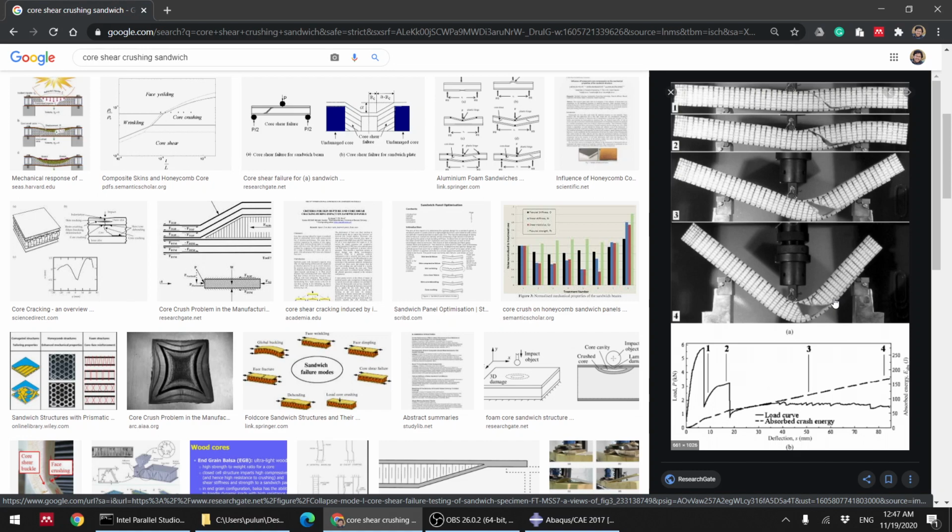If you calculate the inertia, I equals 1/12 b h cubed, your h is way bigger because you have this large cross section, and it's light because the core is made from foam, since it's not supposed to sustain any load. When you're doing bending, the maximum stress is on the skin, not at the neutral axis. The neutral axis has zero stress. So why put material there, right? That's why we put a foam core, or a very soft core.